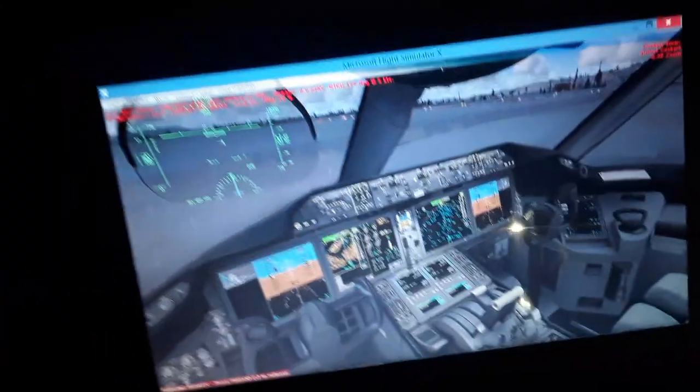So we use the flight management computer. I input all the data of the aircraft for this flight. That includes the takeoff gross weight, the empty weight plus the passengers plus the cargo plus the fuel on board, the trip fuel, the reserve fuel, and the taxi fuel. Where the fuel is stored on the left and the right wing. How much is, like, 30% right now for this flight in the left and right wing tank. The center tank, if it is balanced between the left and the right wing. Also the cargo in the compartments and the passengers.